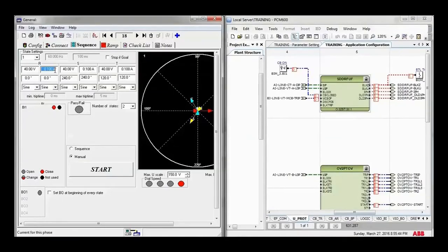What will I do? The current cells are at 0. Okay, I will inject a binary input. Here, I injected the binary input for the breaker close. I will not inject currents. Okay, you will inject healthy voltages, all greater than UC. But after that, when you create an imbalance, what will happen? The block U will trigger, right or wrong?